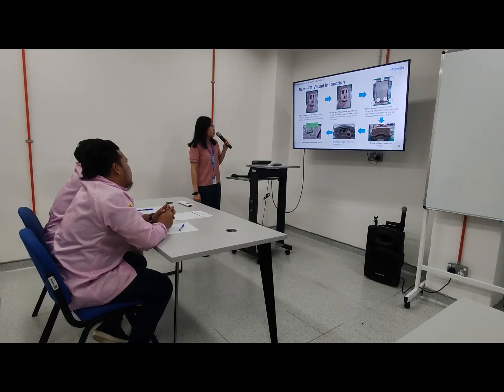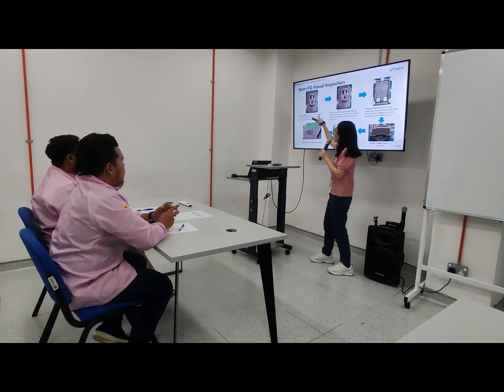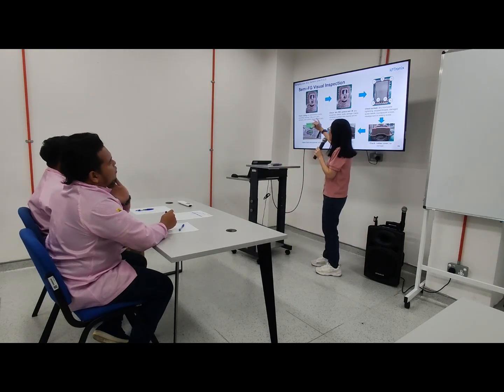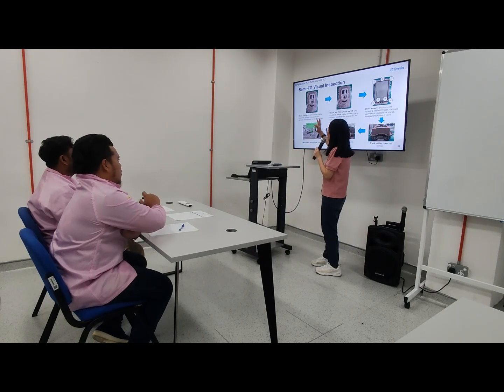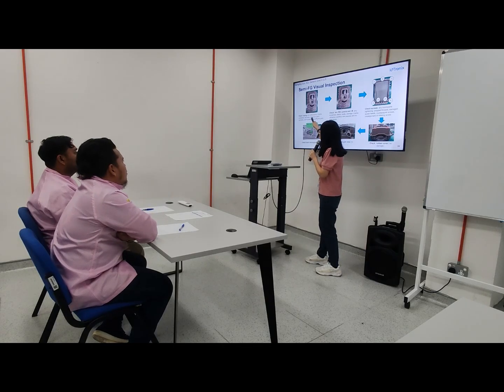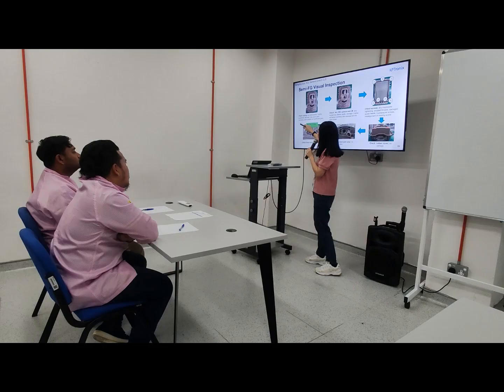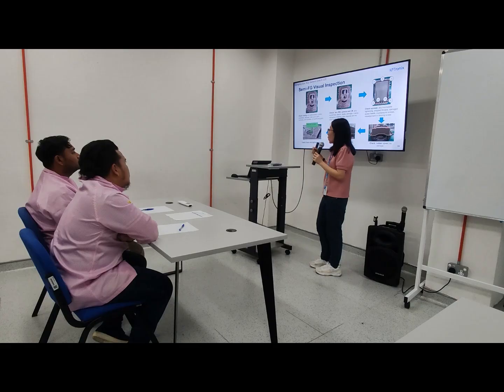First is the semi-FG visual inspection. Okay, first step, we check the casing first. Checking the casing means checking the front, the back, the top, bottom, and the two sides. For the casing, we check for any deformation, crack, scratch, damage, hole, painting defects, paint splash, or insufficient paint.